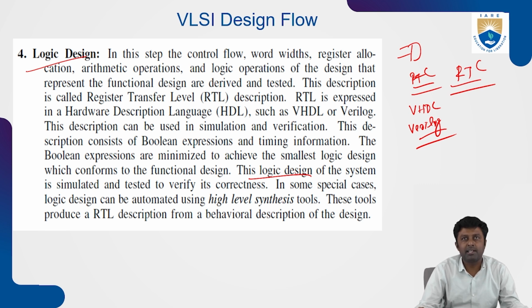The Boolean expressions are minimized to achieve a small logic design which conforms to the functional design. This logic design of the system is simulated and tested to verify the correctness of the design. For whatever specifications we have noted down, we'll be writing the Verilog or VHDL code, and that will be synthesized.